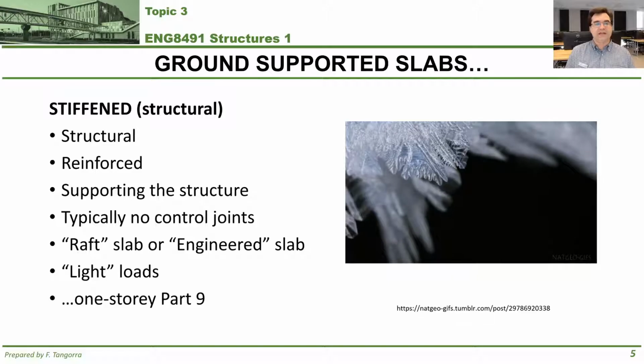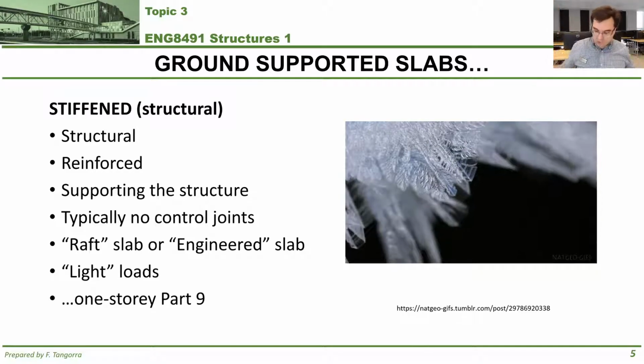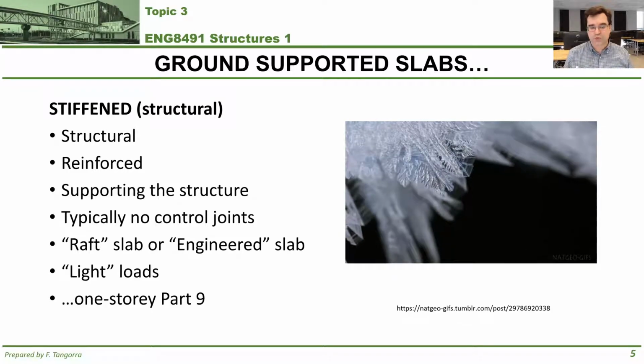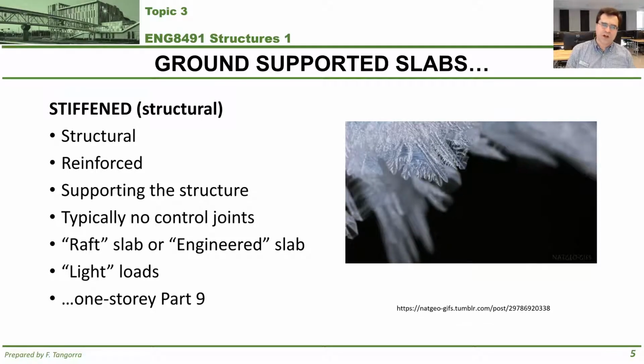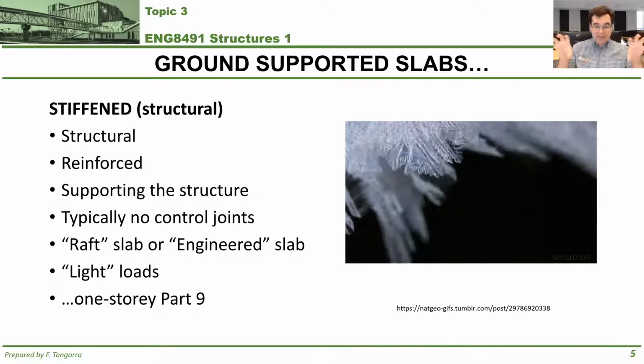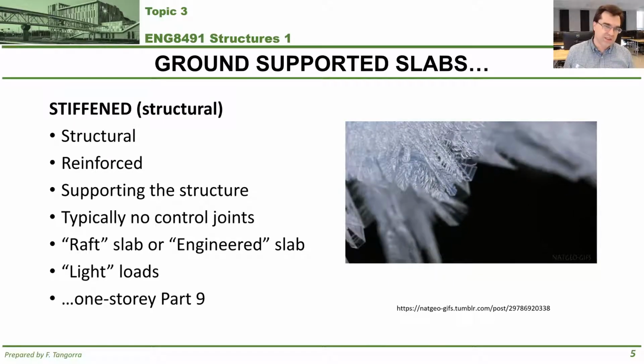And to do that for a structural slab, it means preparing the soil to a fair bit of depth below it. Now at this point, excavation costs related to construction are such a small portion that simply digging down deep enough to put your footings below frost grade is way more cost effective than the extensive engineering analysis and design that's required to actually do a slab rather than a foundation and footing type design.